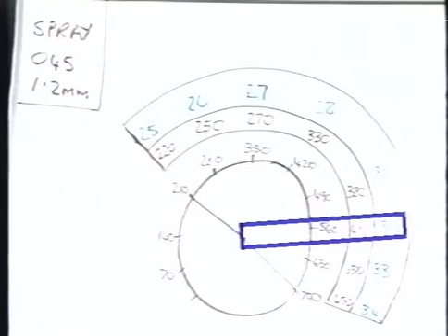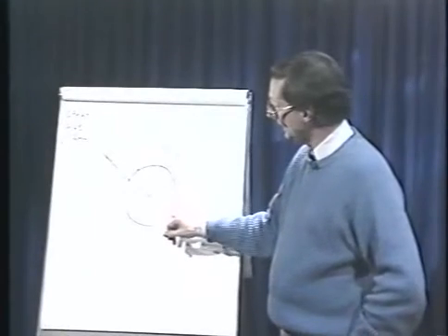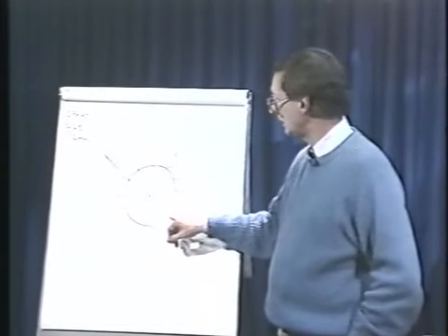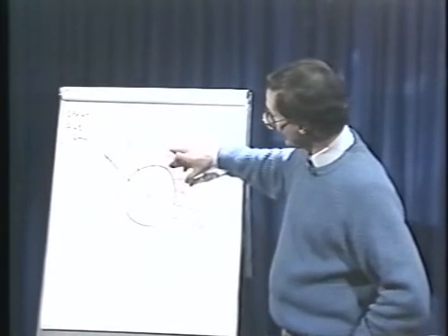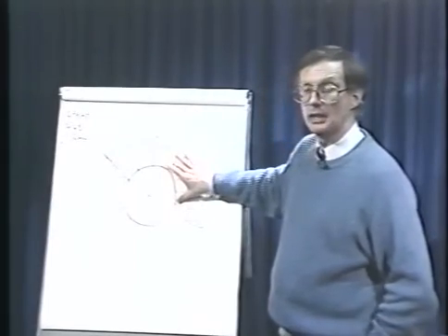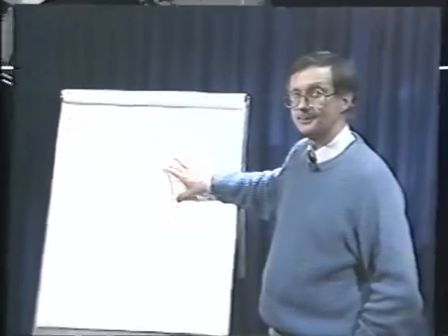Once you open up wide open with an 045, you start to get a turbulence effect on the weld puddle down at the higher end. Most of the welding with 045 is done between the 1 and 4 o'clock position on high deposition work.